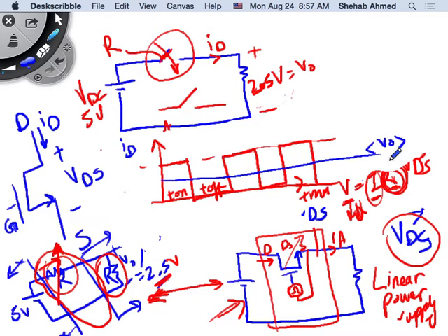But of course, I'm not doing the same thing anymore, right? Here I'm delivering a nice, smooth 2.5 volts to the load. Versus here, what am I doing? I'm giving this load something that looks like a pulsed waveform of 5 volts, 0, 5 volts, 0, 5 volts, 0. It's not equivalent, right? But what do you think you can add that will change this waveform to this? A filter, right? And that's exactly what we would add here, some sort of filtering stage.